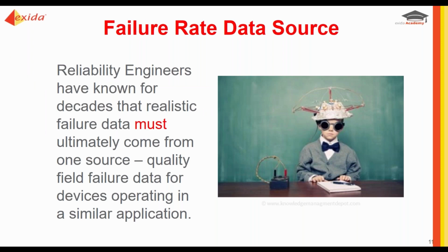When we talk about failure rates, reliability engineers seem to know this, but it seems to be taken for granted. Failure data must come from one type of source, and that needs to be quality field failure data operating in a similar application. What does that mean? Well, when you're doing your analysis, make sure you're always going to do an apples to apples comparison.